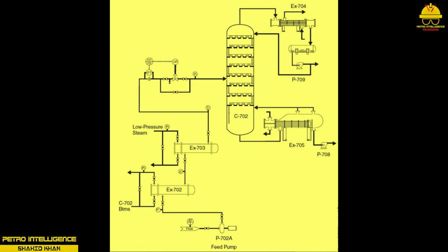During startup, cold feed is sent to the column at 50 GPM to allow the steam heating systems to be engaged. As cold feed enters the column, it drops from the feed tray to the bottom of the column. The bottom outlet line feeds a kettle reboiler located at the base of the column. As the level rises in the column, it simultaneously rises in the reboiler. Steam flow is open to the tube side of the kettle reboiler X705. As the temperature starts to increase, the flow rate is increased in 50 GPM increments up to 200 GPM on FIC 702.